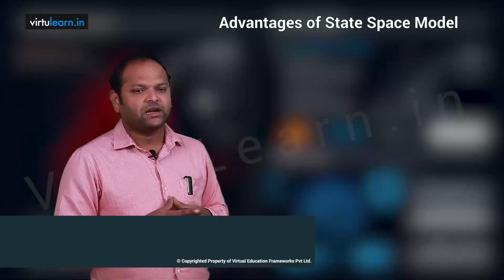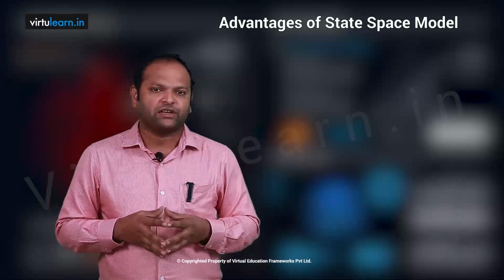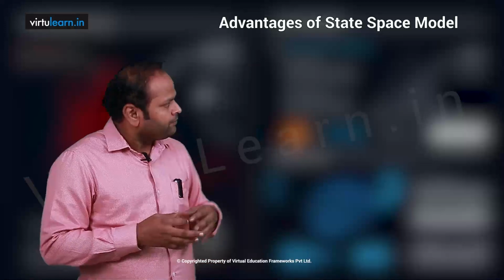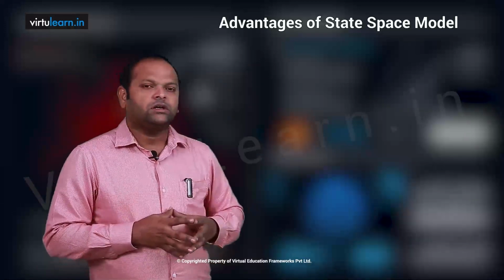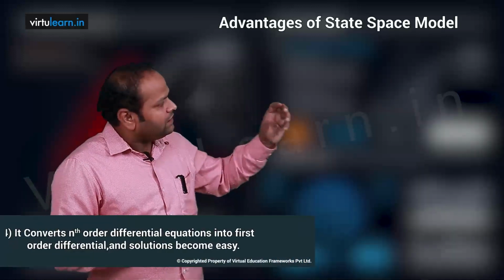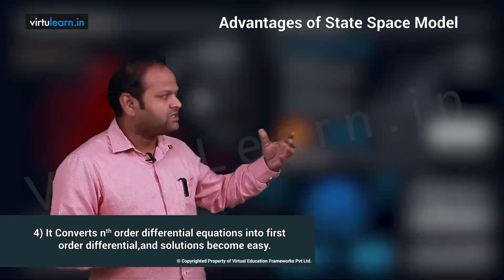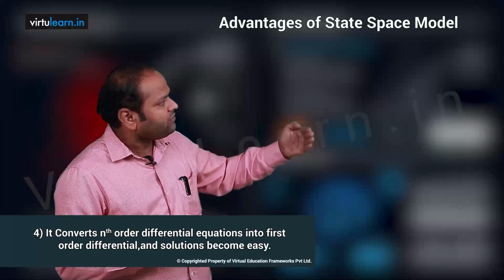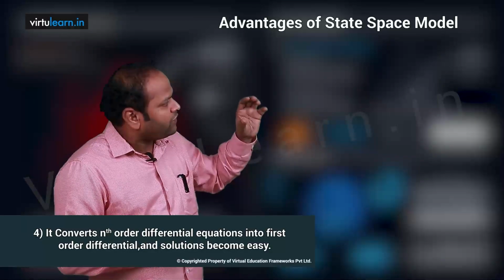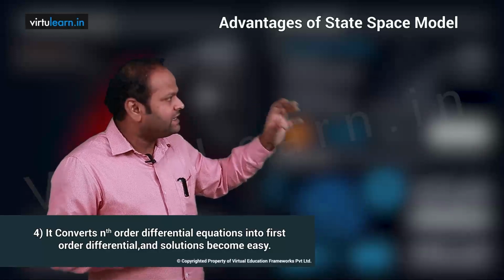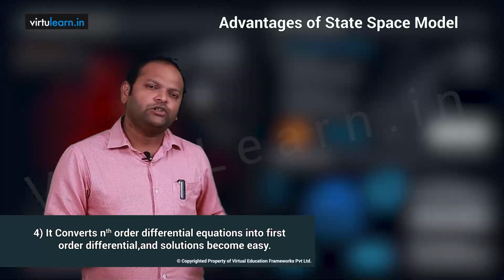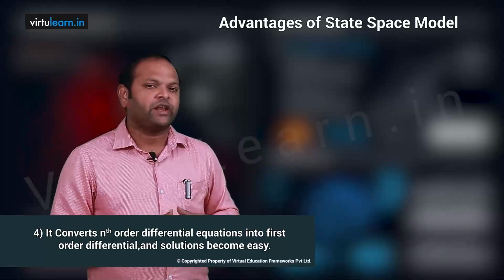That is what the initial condition is. We are taking care of the initial conditions, whereas in the transfer function we simply ignore them. Another important advantage of a state space model is this: if you have an nth order differential equation, it is converted into n first order differential equations, and the solution for a first order differential equation is very easy.